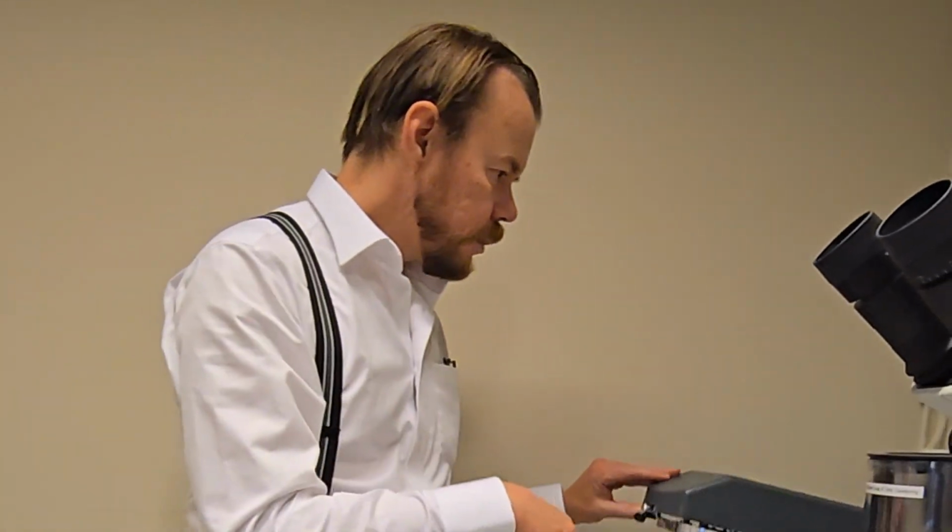So a more modern way is to use a sputter. A sputter works more or less like a spray can. It creates a metallic spray coming down from above onto the sample, and that is a very controlled method. The spraying goes on continuously over time. So either you can just run it for a certain amount of time, but an even better way, if you come closer here,